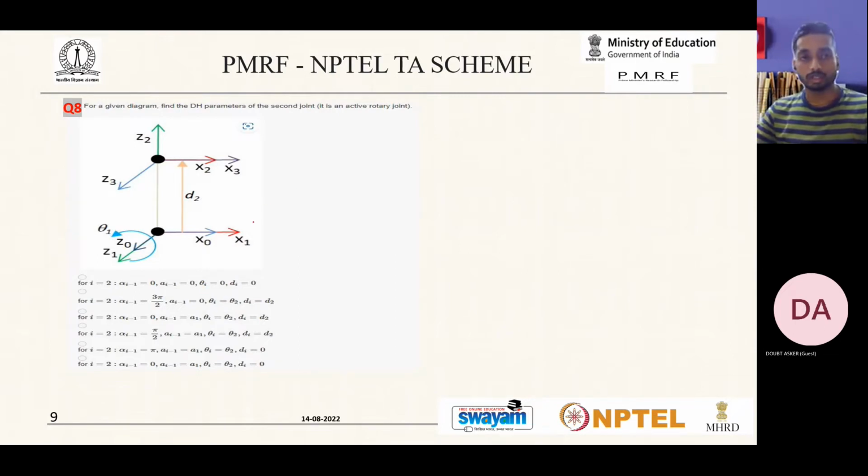This is another question where we have to again find the DH parameters. So here also, how many frames do we have? We have Z0, Z1, Z3, right? And Z2. So let us find for all these. Again, for DH parameters, first we have to make this table. So let us make the table.